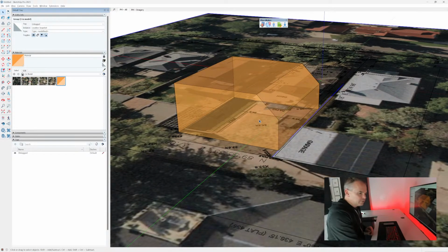And so I guess what we'll do is take a look. What are we doing now? We've got to do a couple things. We're not done yet. We want to start working with our ConDoc Tools extension to add in the tags that we're going to be using. That way we can chip away at the visibility of some of this stuff, like put some things on the background layer and the context layer tag, get it out of our way, and set ourselves up for working with our Medeek BIM suite tools.